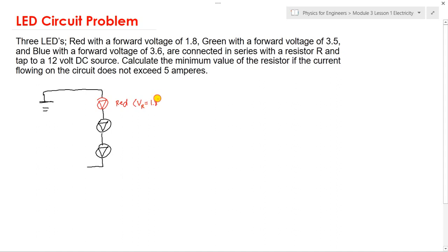We are going to denote this as VR, meaning the voltage on this red LED. So VR. Anyways, I got this from its data sheet. So for every LED class, you buy it with a data sheet and it's standard for all. So you can really use this if you want to light it up. For all red LEDs, the forward voltage range is 1.8.